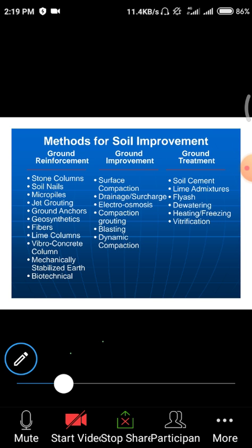That means in a few parts of buildings we obtain cracks due to less bonding between silica and calcium. That means calcium which is present in the cement, and silica which is present in the sand. If there is proper bonding, we obtain calcium silicate hydrate gel, CSH gel, which we studied in concrete technology. If the CSH gel formation is proper, there are no cracks in the particular structure.